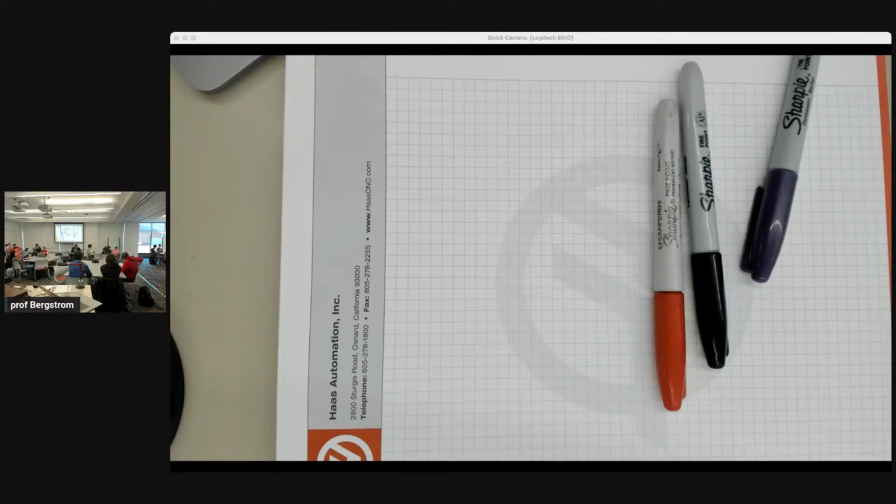So do the steps on the checklist. Today's about machine tool motion, setup, and crashes in CNC machine tools. The checklist is about avoiding those crashes. If you've done those steps, you may not make the part you wanted, but the part you make will probably not break the machine tool.